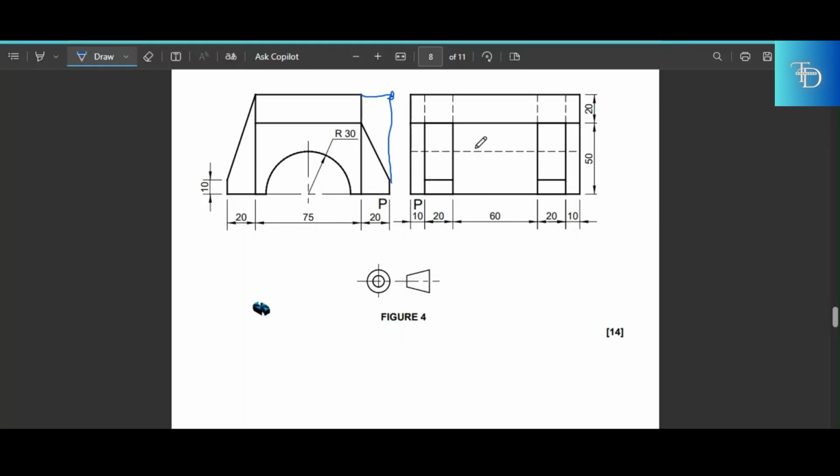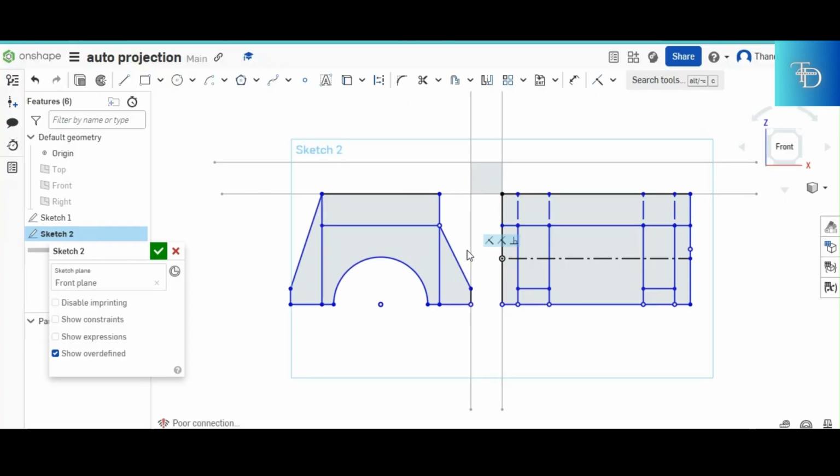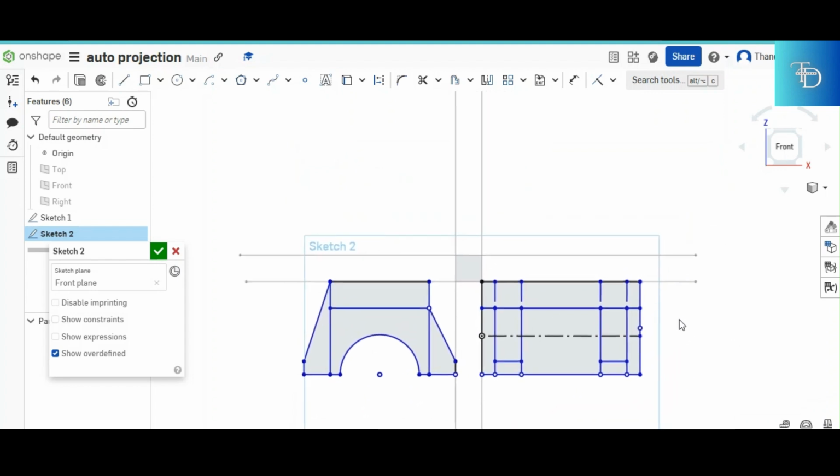So now you copy and paste your views, and then from there you start paying attention, because that's whereby I'll be explaining what to do from there. So there you go. We have our views copied and pasted on your answer sheet right now. You took everything as it is, you placed it on your answer sheet. You see, there is that corner that I was telling you about. That corner right there. You see how we didn't use that corner? Because if we use that corner, this thing was gonna shift to there, and then this ear was going to interfere with our view. So you always extend the corners if you have something that has an opening, has a space like that. So what do they need from us here?